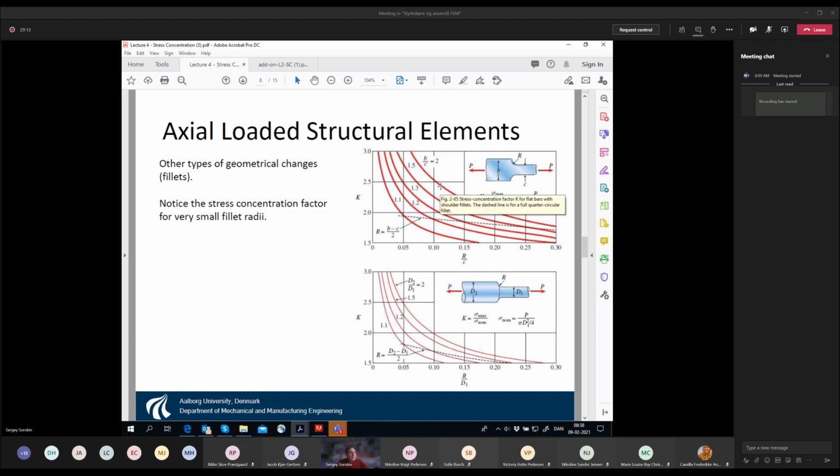They were also verified by the experiments, but you can also do these kinds of things using the finite element method. So one of the possibilities in using the finite element method is that if you introduce a mesh and then apply these forces, then you are able to calculate stresses everywhere in this specimen. And then in particular, if you come to these points, then you see that this stress concentration factor we find from the finite elements agrees with these predictions.